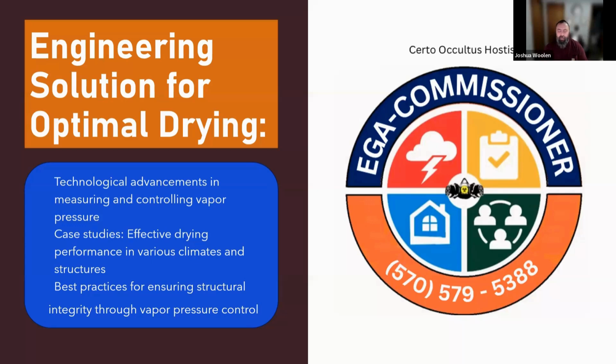It can use the HVAC system within the building to raise the temperature to a comfortable temperature that allows for the difference in the vapor pressure of the environmental air and the vapor pressure in materials to have a difference that causes the release of the moisture from the materials. So